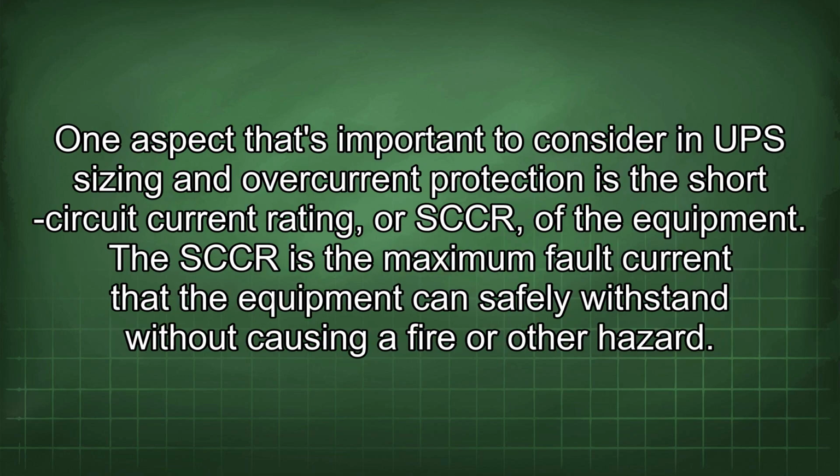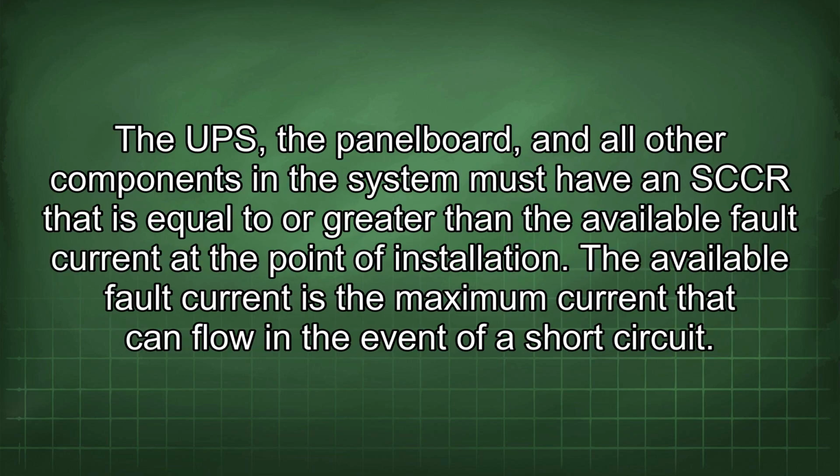One aspect that's important to consider in UPS sizing and overcurrent protection is the short-circuit current rating, or SCCR, of the equipment. The SCCR is the maximum fault current that the equipment can safely withstand without causing a fire or other hazard. The UPS, the panel board, and all other components in the system must have an SCCR that is equal to or greater than the available fault current at the point of installation.